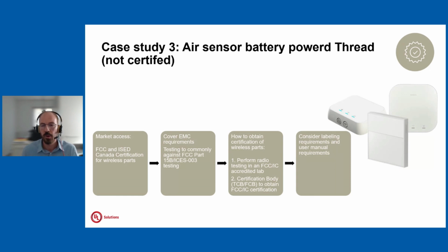So we will need to do EMC testing. So EMC testing is something you need to consider in the 3 stages. The difference in this stage is because we are going to do an FCC and Industry Canada certification, the supplier declaration of conformity will not be applicable as declaration of conformity, but because we are going to go through a certification, which is a stronger process. However, the EMC testing will need to be done anyway. So in the three scenarios, you have a commonality, which is EMC testing needs to be addressed every time.